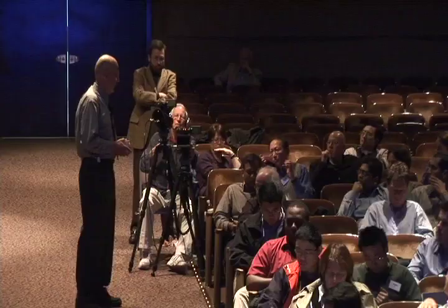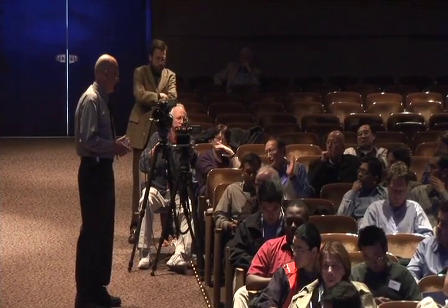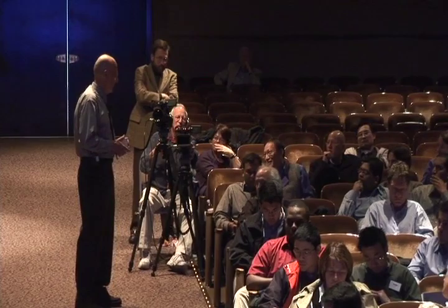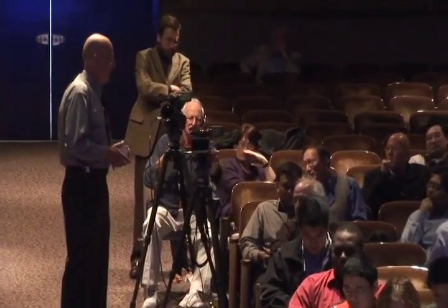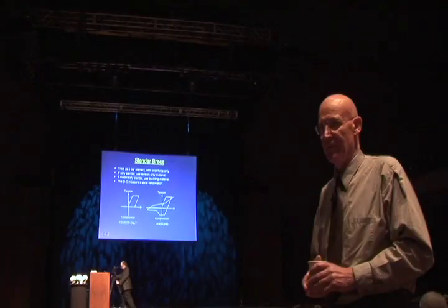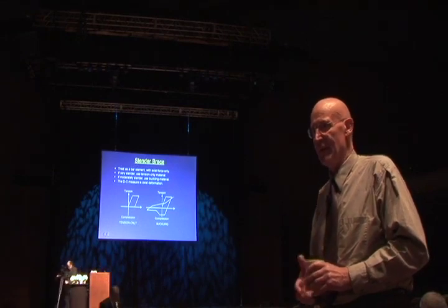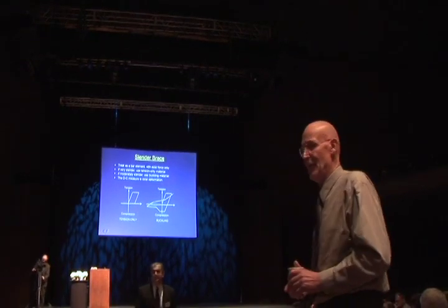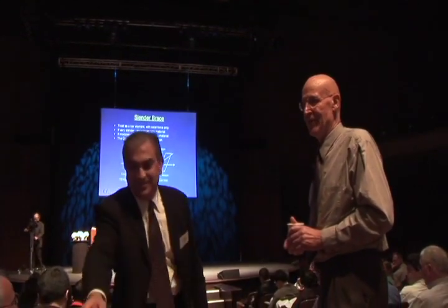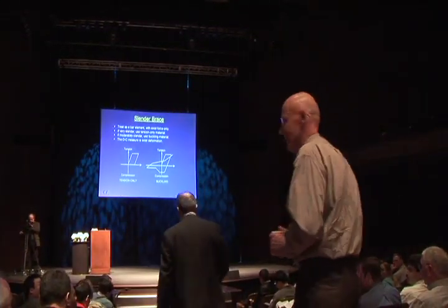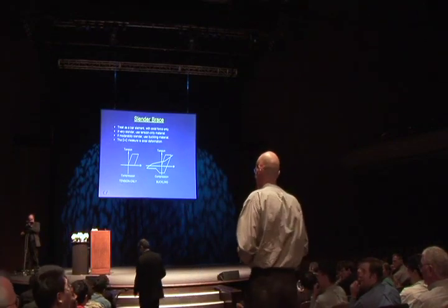Have you tried different models for different frame elements? Within the same structure, you can do that if you want to. Yeah, people do that. It has been done. You don't have to use only the chord rotation model or only plastic hinge models. You can mix them. Different elements can have completely different models if you want. I was afraid your original question was whether I did a comparison of different models as if they made very much difference, and that's a can of worms I'd rather not open. Let somebody else worry about that.